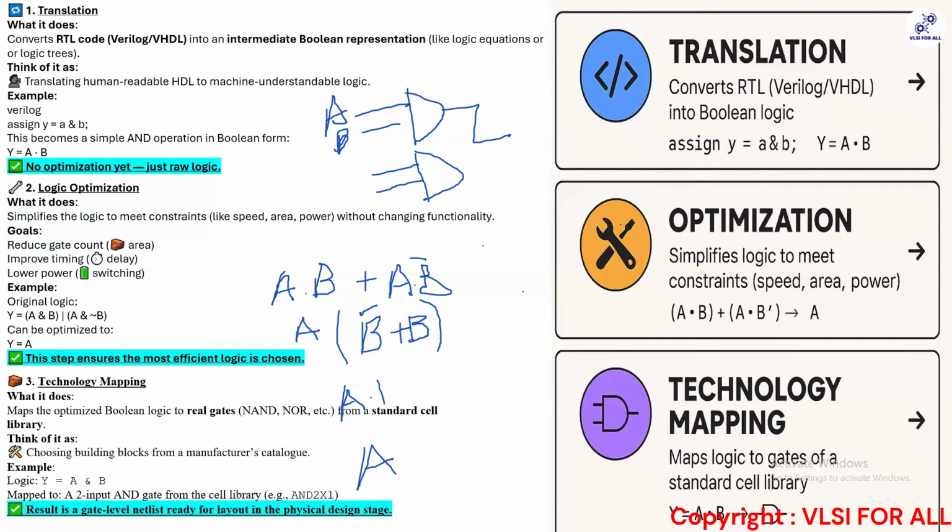This library is made by some standard cell library characterization team. They do this, and how they design it and how they know it is a complete, entirely different ballpark. For example, if an AND gate is under this much voltage, how will this AND gate behave? If it is under higher voltage, it will generate the output faster, because the higher your voltage, the faster the speed. Lower the delay. So the library you are providing covers different modes and different corners.